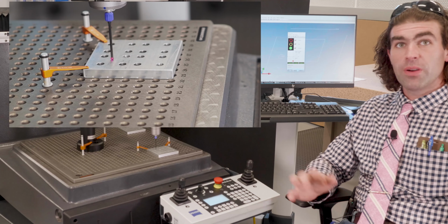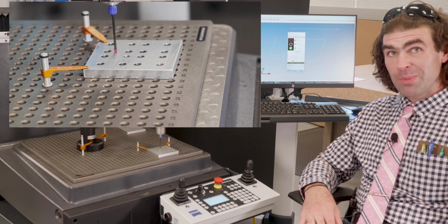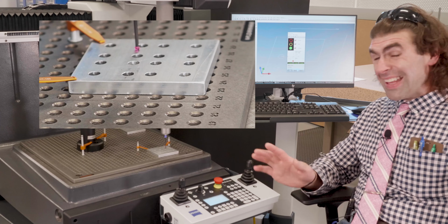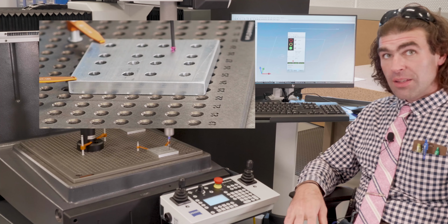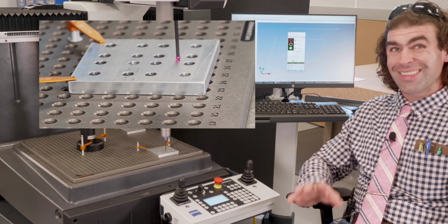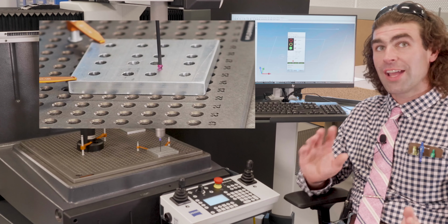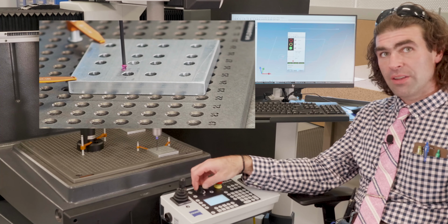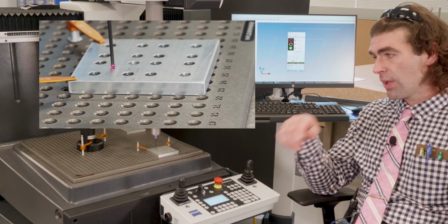And then the computer is going to do its thing. It'll do all the features we had in the alignment, and it's going to go ahead and check those new features. I want to keep an eye on it just to make sure, again, it doesn't smash into anything. Sometimes it can do wacky stuff. In the future, we'll get more into the clearance planes and being able to check and make sure you're not going to smash into something. But for now, just keep your hand on the speed wheel anytime it's changing features, okay?